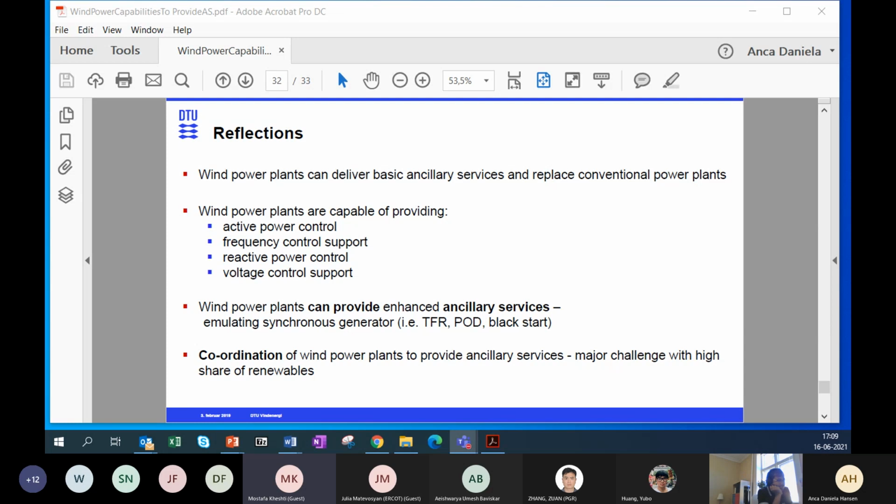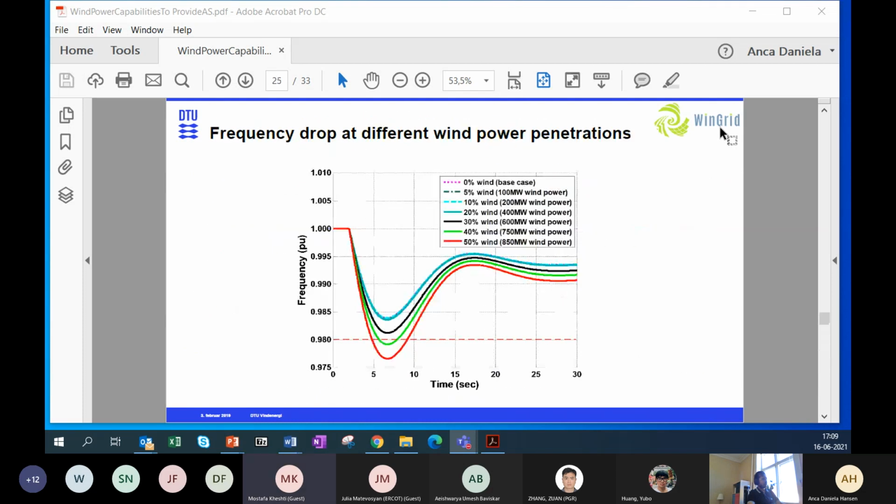I have a couple of questions on the ancillary services of wind power plants. Actually, it's more of a comment than a question, but I would like to have your opinion on it. When wind turbines are participating in inertial control or frequency regulation, they will go through a stage of re-acceleration or recovery, when the rotor speed will try to go back to the maximum power point tracking. However, in a lot of literature, almost all of it actually, this recovery stage takes 2 minutes. But the problem in reality is that the wind speed is not constant, which is different from academia.